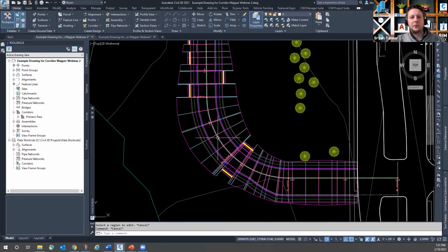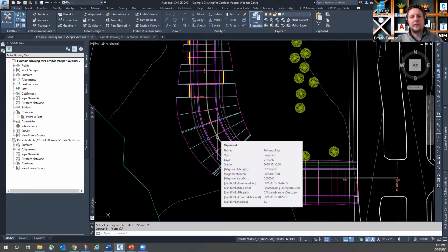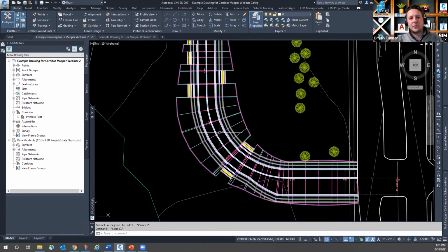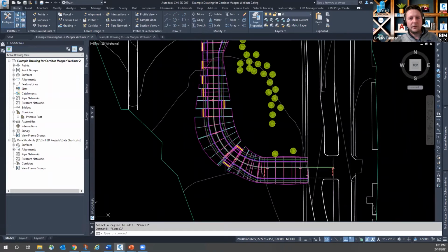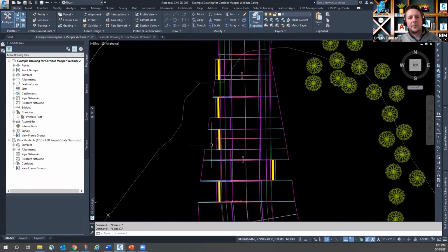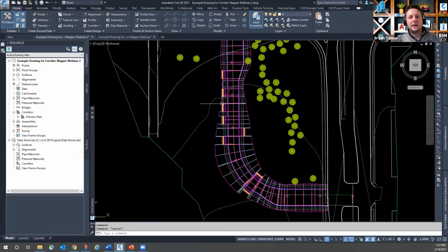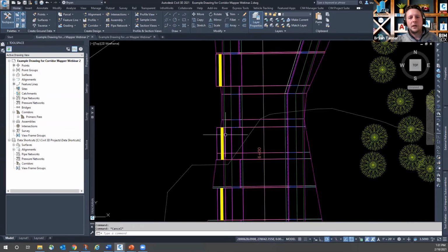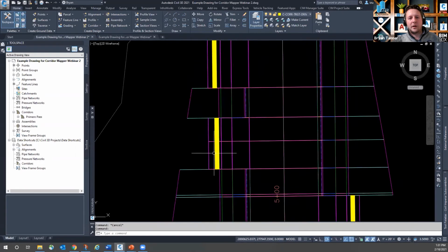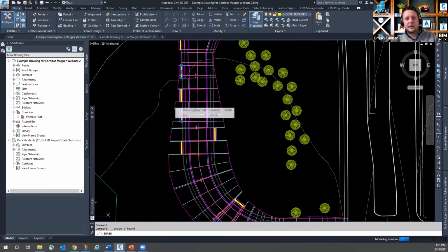And what we have available to us is more of a manual process, whether by individual selection or selection by layer of a static group of objects that are connected to our corridor targeting. So taking a step back here, I'm going to remove a couple of these additional targets that I copied just so that we can explore what we can do with some other tools that are available to us.